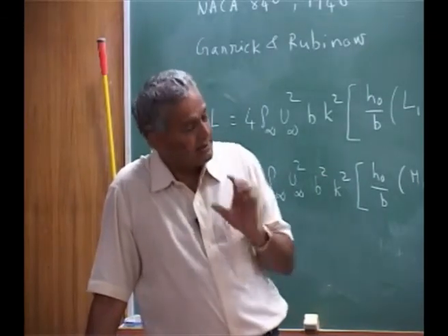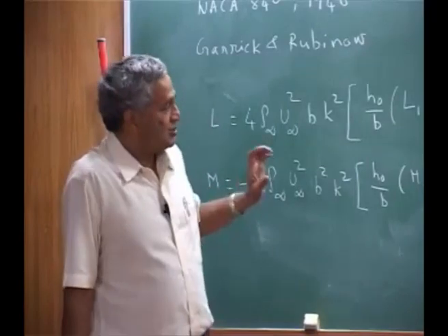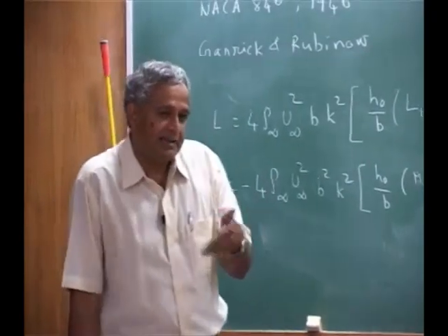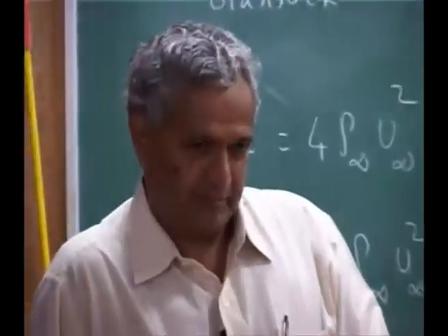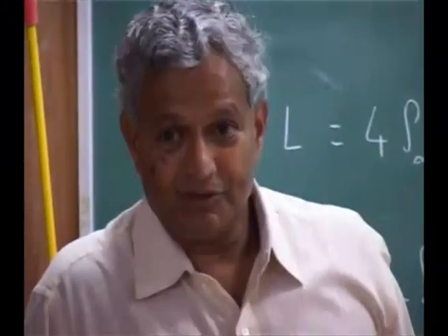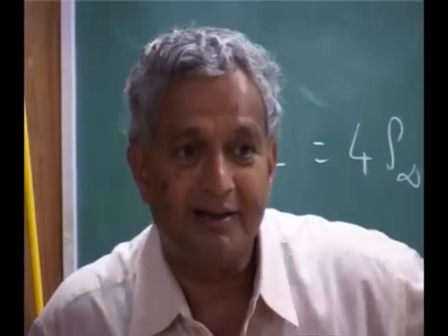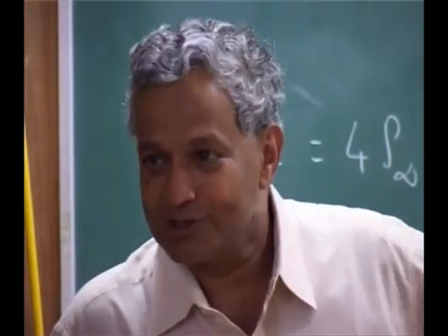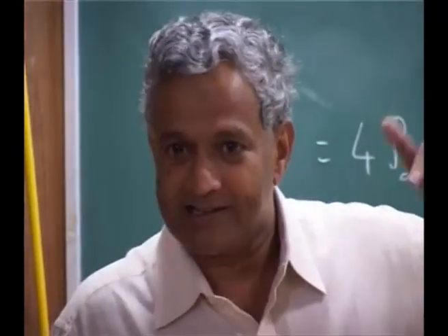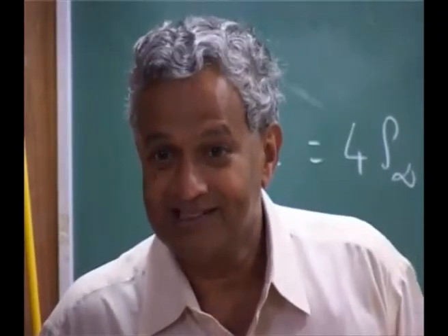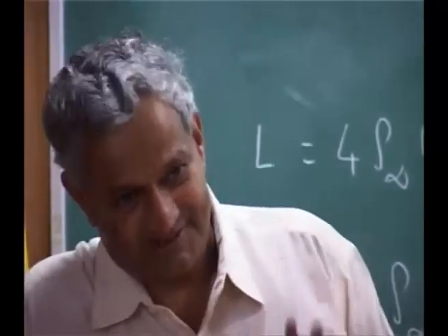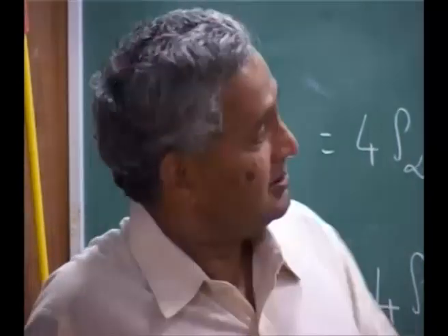This is similar to that, because there is a delay in the motion of the fluid which is going around the aerofoil. If the aerofoil is executing harmonic motion, the lift will not be at the same phase. It will have a different phase depending on your omega.